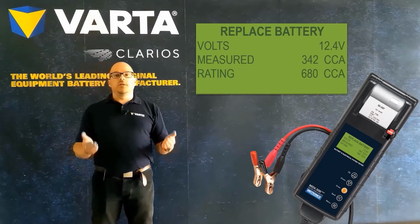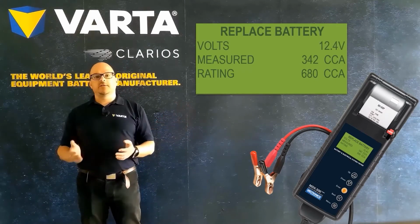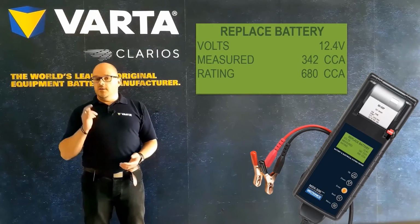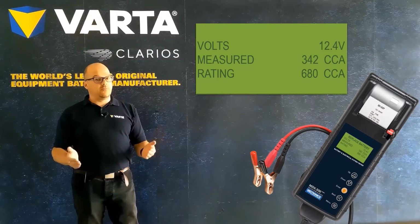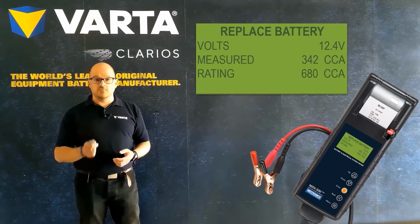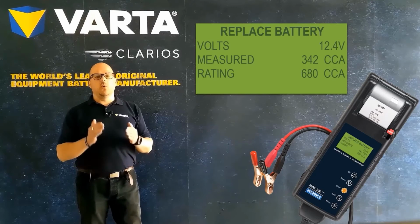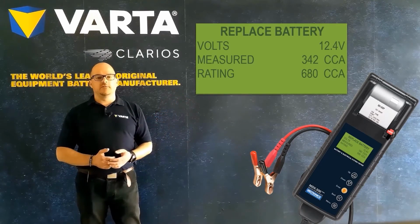This, also coupled with the low battery voltage of just 12.4 volts, indicates that the battery is unable to provide continued power to crank the engine and supply power when the engine is stopped. This means that the battery needs replacing. Understanding this will help you to understand the condition of the battery if you ever use a tester that doesn't provide a result other than the figures measured. However, a good quality tester will always show you a worded result as well as the figures measured.